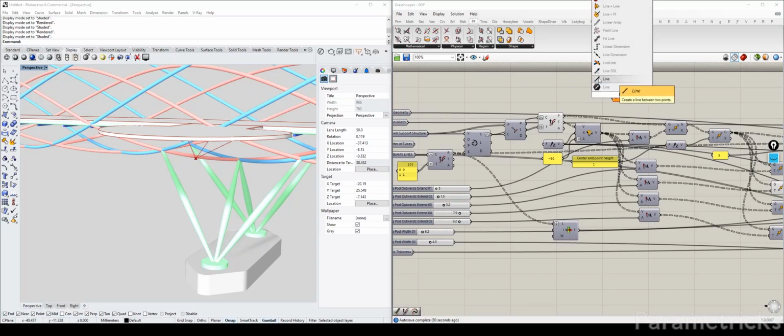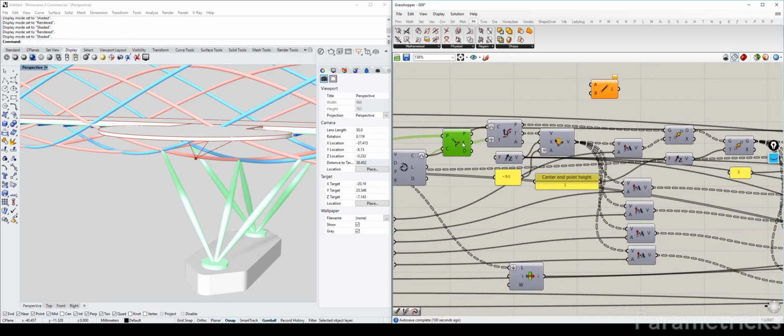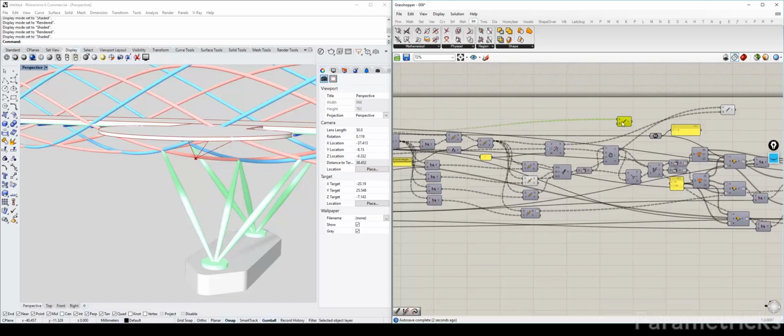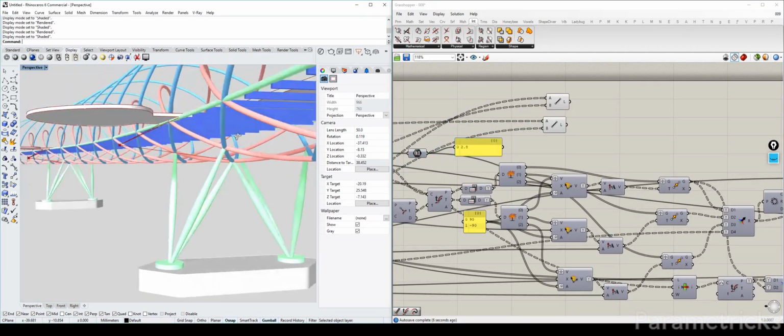So let's just create a line from that. Doesn't matter which one you take, well, not really, because they're all the same point. So you can either take this, that, or this. It's totally up to you. Since we haven't done anything to modify the point position itself, we only used it to gain additional information such as the parameter for the curve in order to get our tangent vector. So let's just take that for a cleaner look. And we have to connect this one, I believe, to this point again. And these two lines make up the support that connects to our helix.